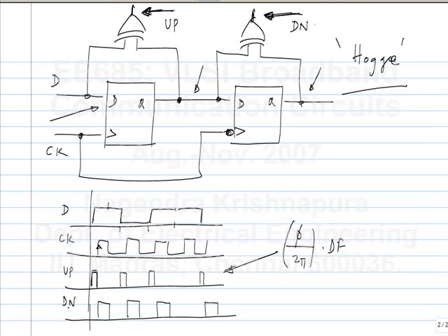So what is this? This is like reducing the gain of the phase detector, isn't it? In the case of the frequency synthesizer, we don't have this. The transition density is 1. In this case we have that also, so that multiplies the phase detector gain. So essentially the phase detector gain is multiplied by the transition density. So that directly appears in the bandwidth of the phase lock loop.